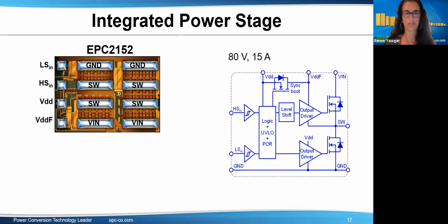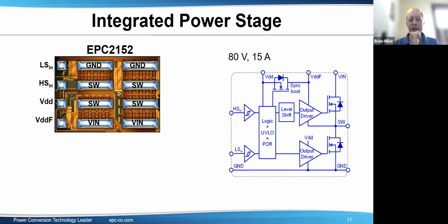Common source inductance affects the driver's speed and efficiency. Is there any way to neutralize it other than reducing it? To reduce it, well, good layout, obviously, but that's reducing it. As I mentioned before, if you have a circuit with a sense resistor, using a driver that connects right to the source, rather than to the ground node, a driver that's referenced to here instead of referenced to ground, that would also do it.